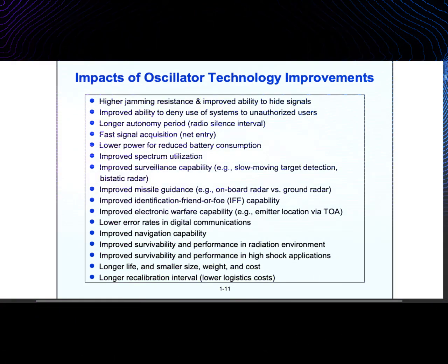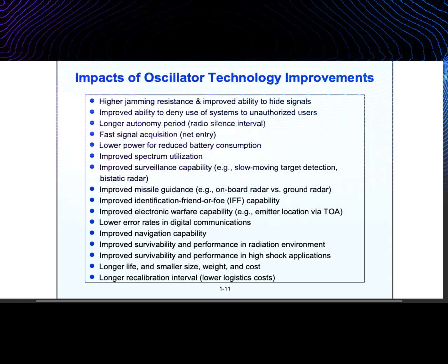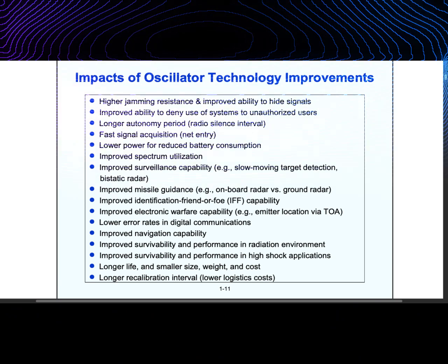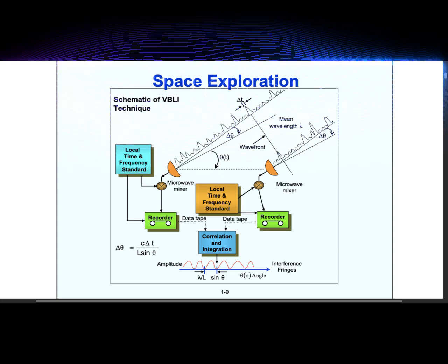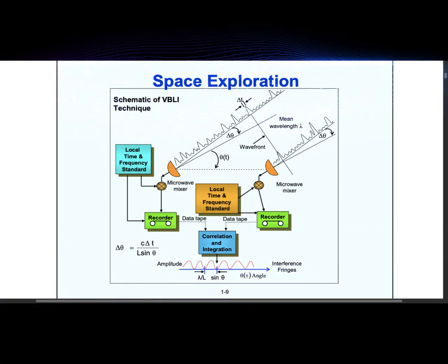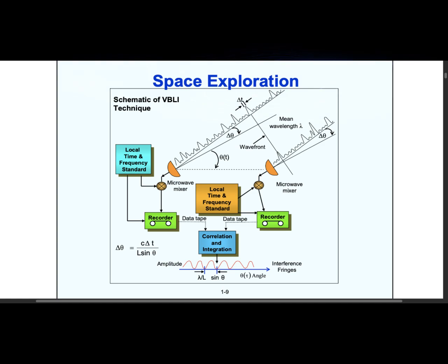Many different substances have been investigated as possible resonators, and for many years quartz has been the preferred material to satisfy the requirements for precise frequency generation. Compared to other resonators like LC circuits, mechanical resonators, ceramic resonators, and more, the mechanical resonator made from quartz materials has been proven to be superior by having a unique combination of properties. These specific quartz crystal properties are both extreme stability over temperature and high repeatability.